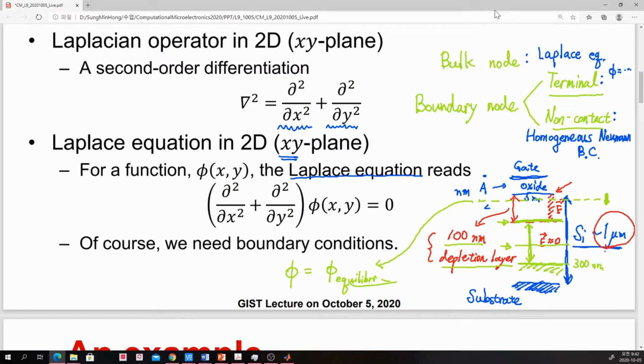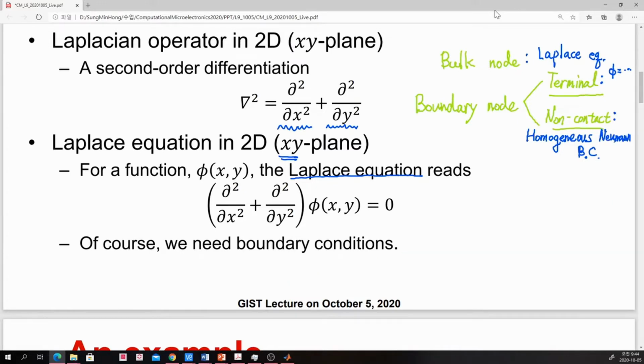I mean that if we have a certain reason where the electric field is still not vanishing, then we have to include that part in our simulation domain. If we just cut the domain and at the boundary we have a strong electric field, that will introduce quite a lot of error in our solution. It is very difficult to predict the exact, maximally efficient position for our simulation. So we have a trade-off.